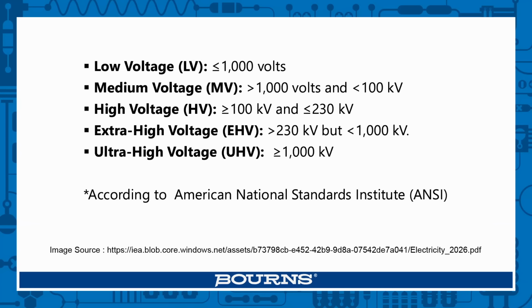And at the same time, we're seeing everything head towards more DC, so HVDC. So let's say, move away from the traditional 50 hertz grid and towards a more high voltage DC supply. One of the reasons for that is that even 50 hertz, which is 50 times per second, introduces problems with the skin effect, which notably causes higher losses in copper conductors. And one way of avoiding that is switching to DC.